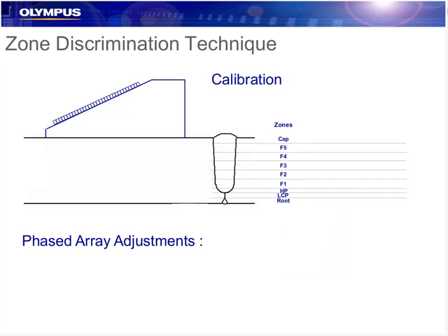So you can see here, depending on the weld geometry, its thickness, etc., we're able to designate zones between 1 and 3 millimeters typically. And we have things like the different fill zones in the weld here. We have a cap channel, hot pass, the root, etc. Depending on the configuration, we'll split that up into zones.